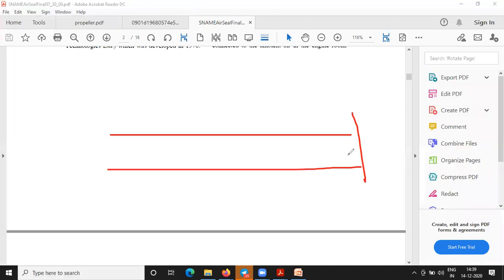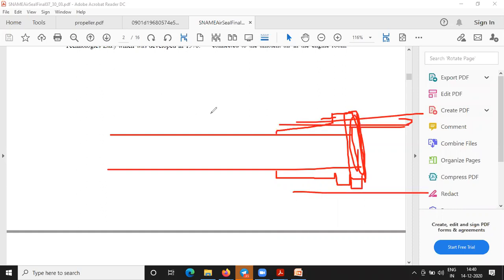Yes sir, this false flange remains. False flange means this is a virtual flange, you have just fitted a flange there, you can remove it out. So chrome liner is here. Now the chrome liner is already damaged and you want to change it, right? That's why you have to remove the chrome liner. What you will do? Yes, sir. Take out this half flange, pull the chrome liner outside, cut it. When you cut it, it will become two halves and you can remove it.